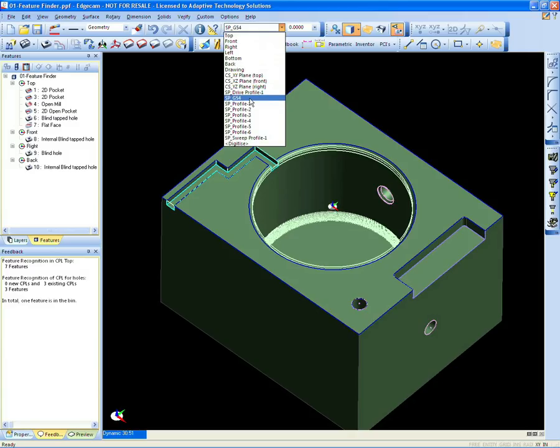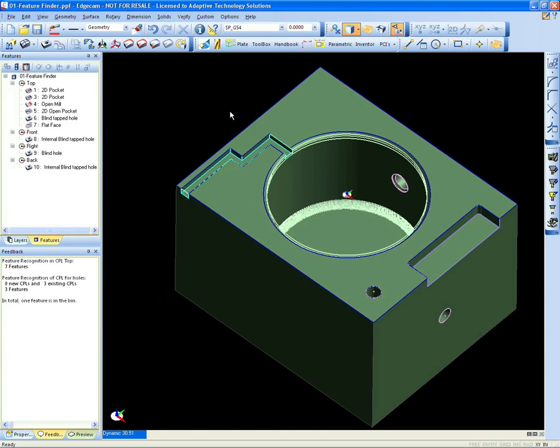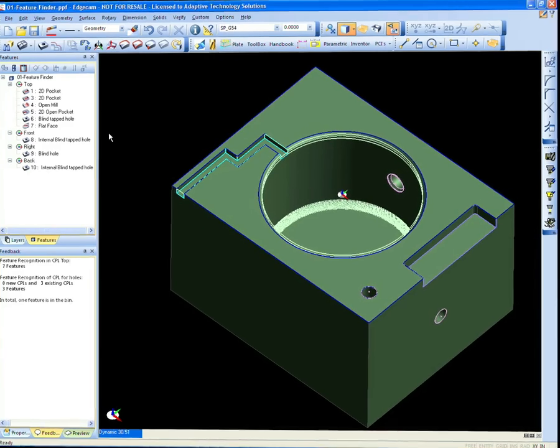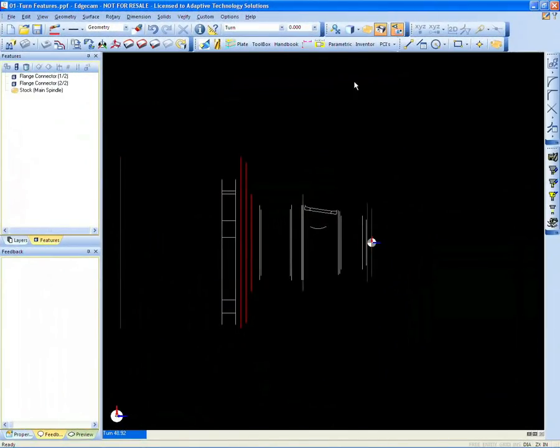All these work planes and sketch planes were used to create this solid model. So again, if you had one just defined as a G54, 55, P1, P2, whatever, you could easily select them from the list. Since it's a user defined CPL, you can rename it as well.